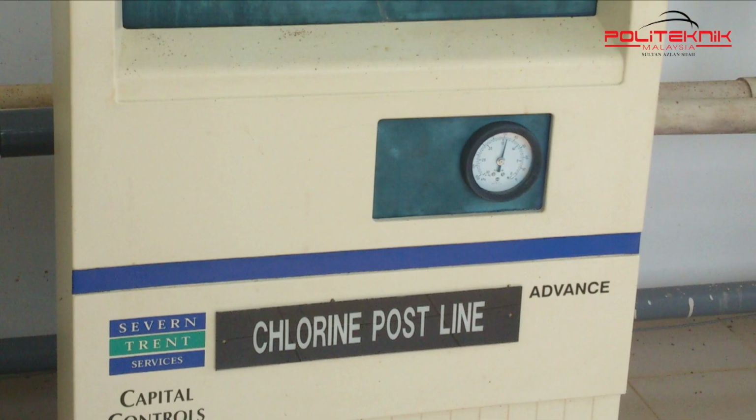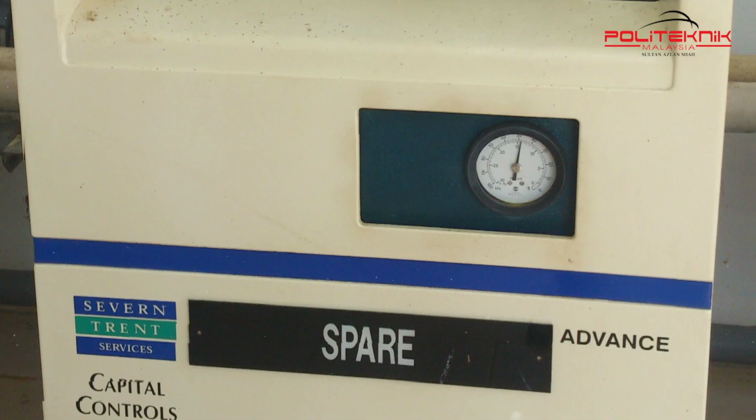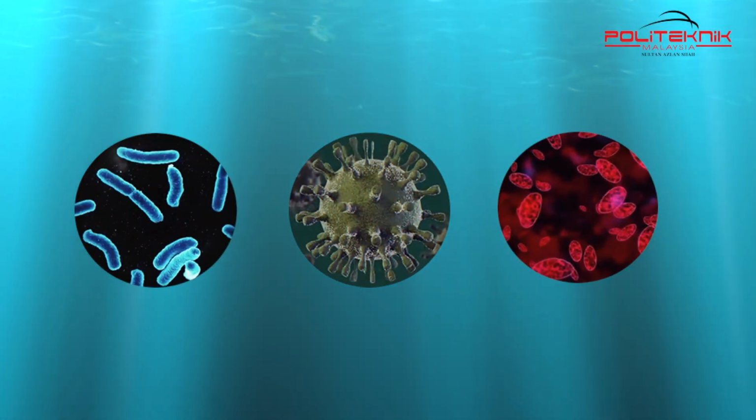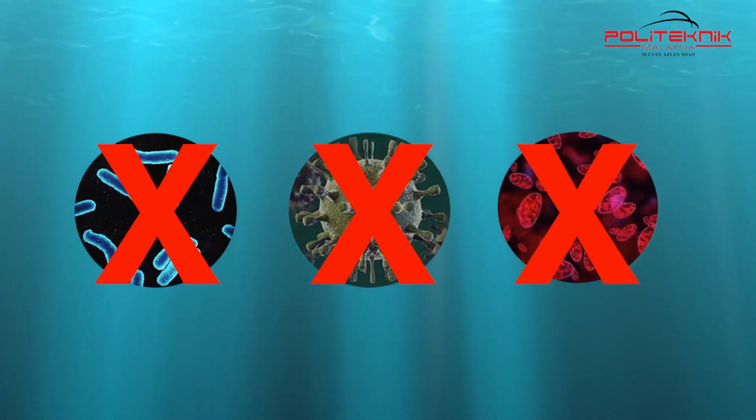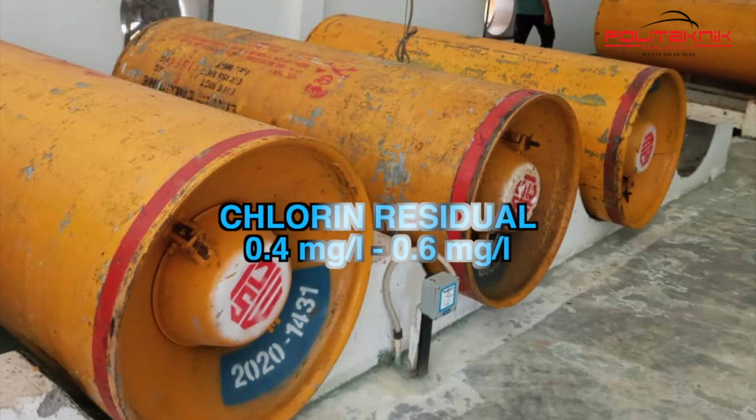Chlorine comes in many different forms including chlorine gas, chlorine dioxide, hypochlorite and others. Water plants monitor the chlorine levels continuously and very carefully in the treated water. Chlorine residual in the water must be 0.4 to 0.6 mg per liter in range.